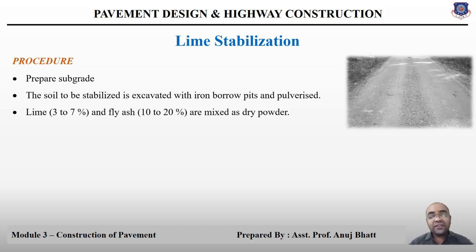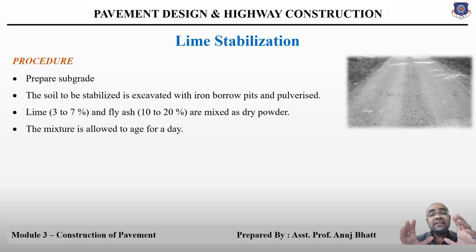After this, that mixture is allowed to age for 24 hours, that is a day. Preconditioning of the soil makes the pulverization process easier, and after keeping this material to age, you have to remix this material again.